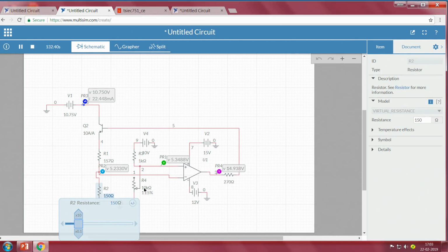So, there is some amount of time the feedback circuit takes to bring the resistance back to the desired condition, so that the temperature across this arm is maintained constant. So, this was about the simulation and how to rig up. Let us see how in a real time scenario we can have the anemometer circuit. Let us blow different temperature air across your load and see how the temperature varies and how your feedback mechanism maintains the temperature around your desired arm at a constant rate.